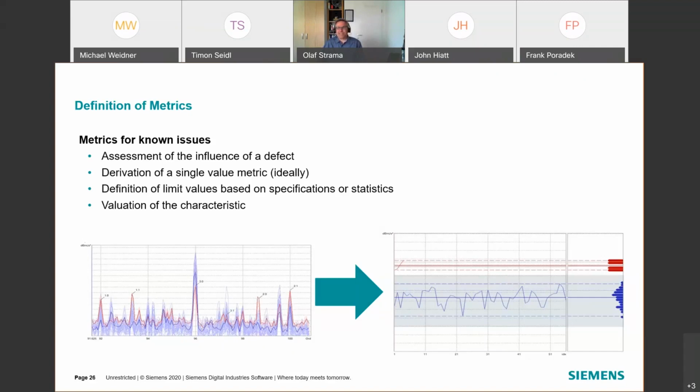So the number of channels for an engine test bench is between 2 and, let's say, 6, not more. And the positions are near the timing drive, near the oil pump, something like that. Wherever there's space. Yes, that's true. Of course, at the end, we are quite limited there.